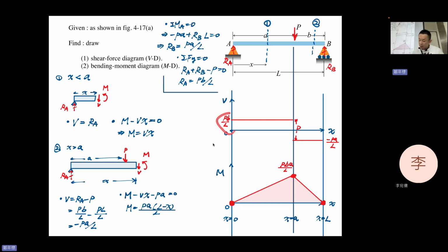Okay, here, shear force. Do you think it will be non-zero here? Of course not, because here is the hinge, here is the support. The support must have a reaction force, especially when you have the P here.